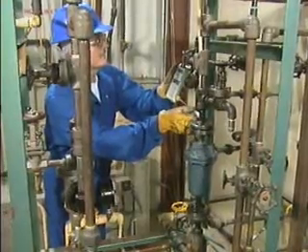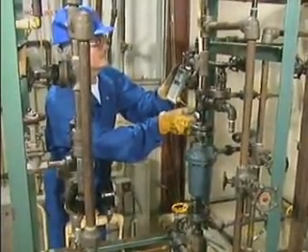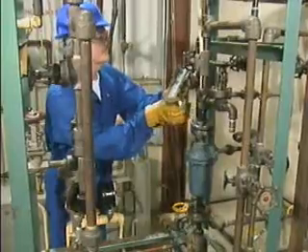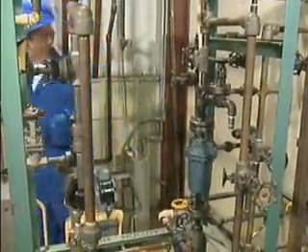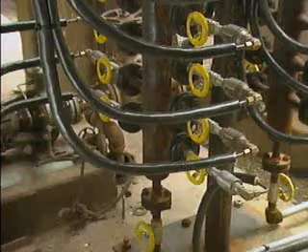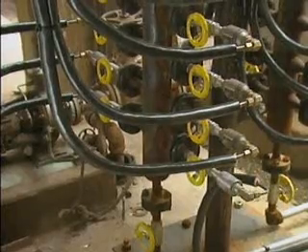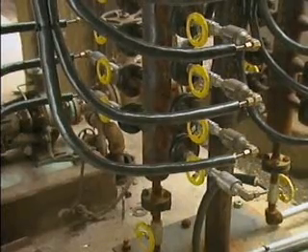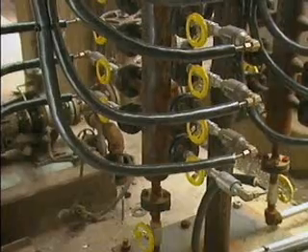If the temperature at the trap outlet is also within the allowable range, trap conditions are probably normal for the temperature inspection part of the trap survey. Trap surveys based on differences between trap inlet and outlet temperatures can be inaccurate in certain situations.